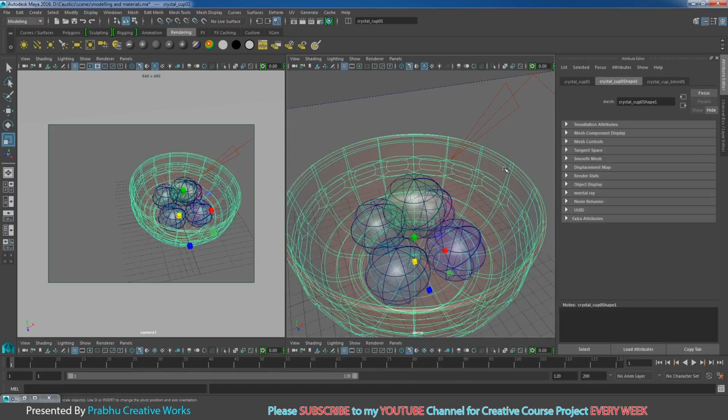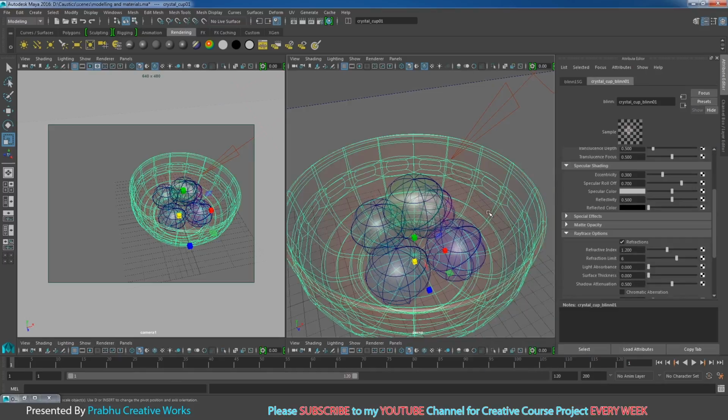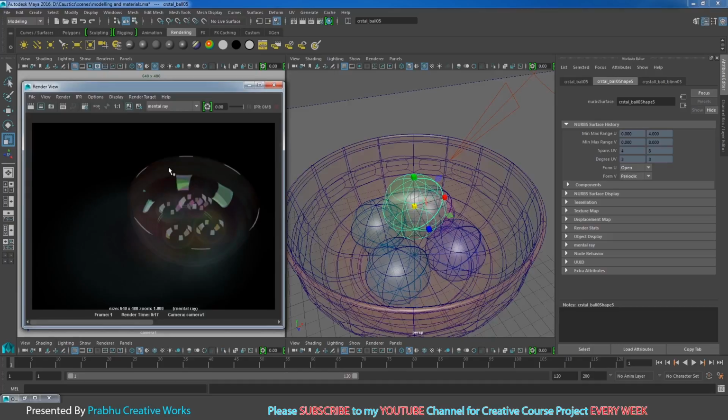I will give 1.2 refraction to my crystal cup because it has some thickness. The others have only one layer, so I will give them 1.1 refraction. So I will select my view, open the render view, keep this image for comparison and click render.